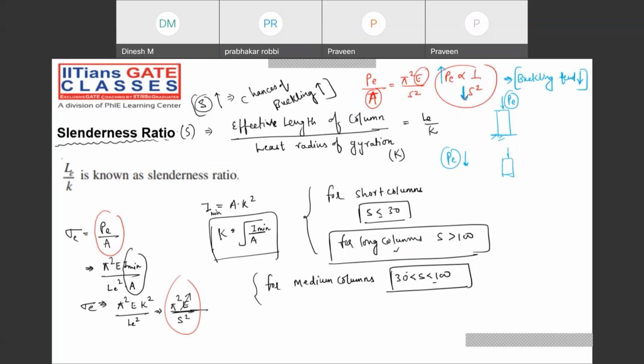So note down very, very important points. The area must be the same in both conditions, and Young's modulus or material must be the same. If you change the material and increase the load, it doesn't guarantee that the same phenomenon holds, whether buckling will happen or not depends on the material. I'm saying for the same material, so Young's modulus will be the same and the area will also be the same, right? So that's a condition actually.